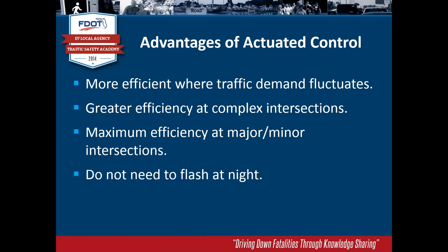And the last bullet here, do not need to flash at night. Many agencies used to flash their signals at night. Most of them have gotten away from it now, again, because of LED signals and other things. Again, you were burning every single signal 24 hours a day, 7 days a week. One of the things that drove agencies to operate intersections in flash mode at night, there's not much traffic out there, and putting it in flash, you only burn half as much power as you do when everything's operating.